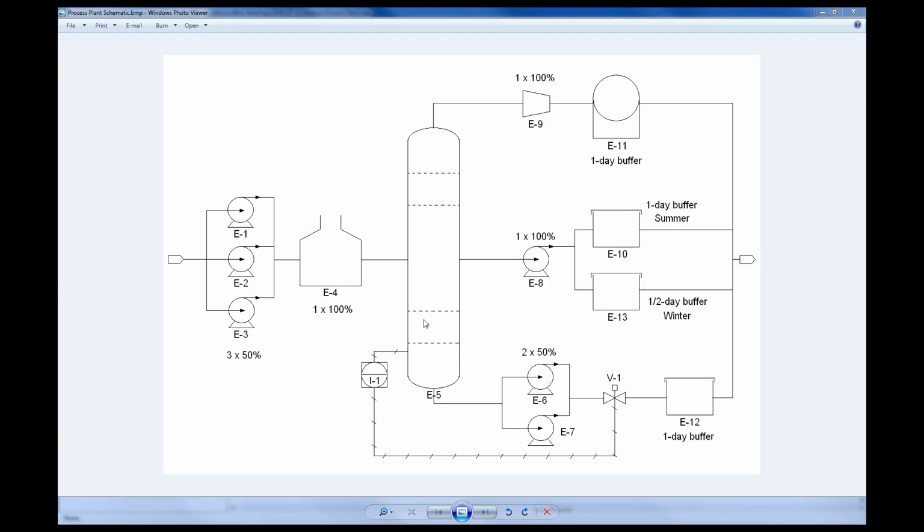And we also have a backup, a relief system. In the event that there's a failure in the fluid pump, we can relieve the pressure vessel via our 2 relief pumps and a relief valve. Provision for these is to avoid an overfill of the reactor vessel, so that we don't accidentally blow it up by having too much pressure, or too much fluid in it. So it's just an emergency safety system.